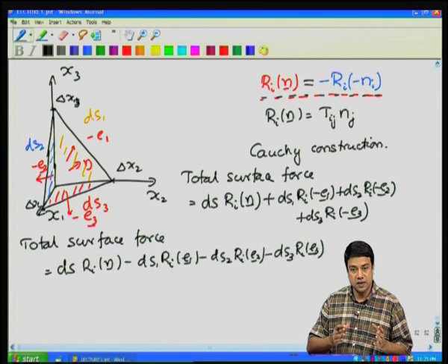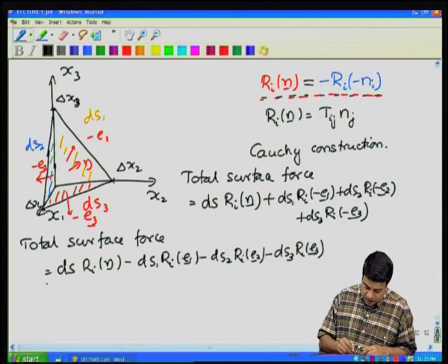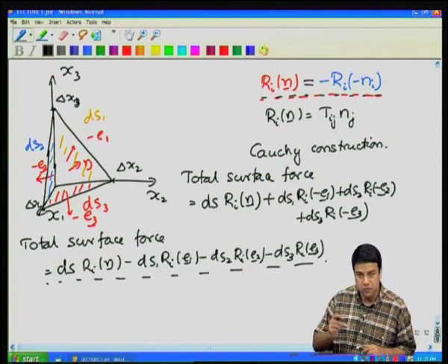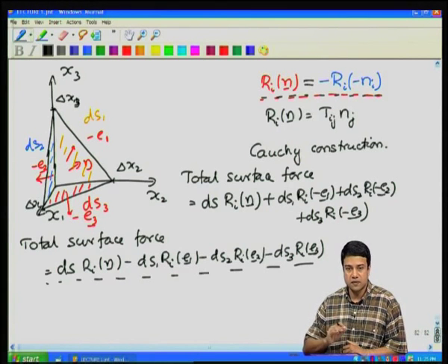Okay. Obviously, the volumetric terms are going to 0 as delta x cubed, surface terms are going to 0 as delta x square. So, the only way that you will be able to retain a balance is if this thing goes to 0 as delta x goes to 0. In other words, I should be able to reduce this surface force into a volumetric form.